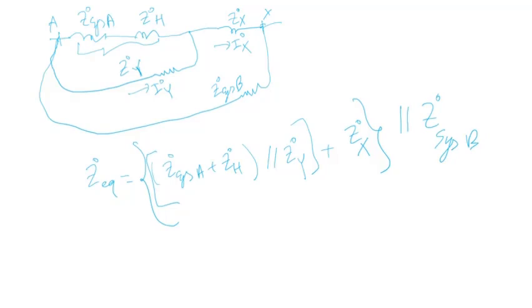So now, basically, I calculated all the equivalent impedances. And note, this here would be known, from the power system. The utility or whoever owns the system would provide this impedance. The transformer manufacturer would provide this and this impedance. The utility or power system owner will provide that.